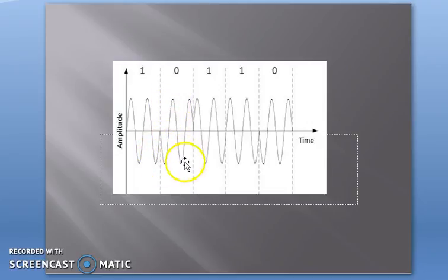So here the phase is changing. Again, if 1 comes, the phase changes. And again 1, which is not new binary data but the already existing one, the phase will not be shifted. Then 0 comes, and again the phase is shifted. So this is how it works, and here also the frequency is not changing and the amplitude is not changing. That is called phase shift keying.